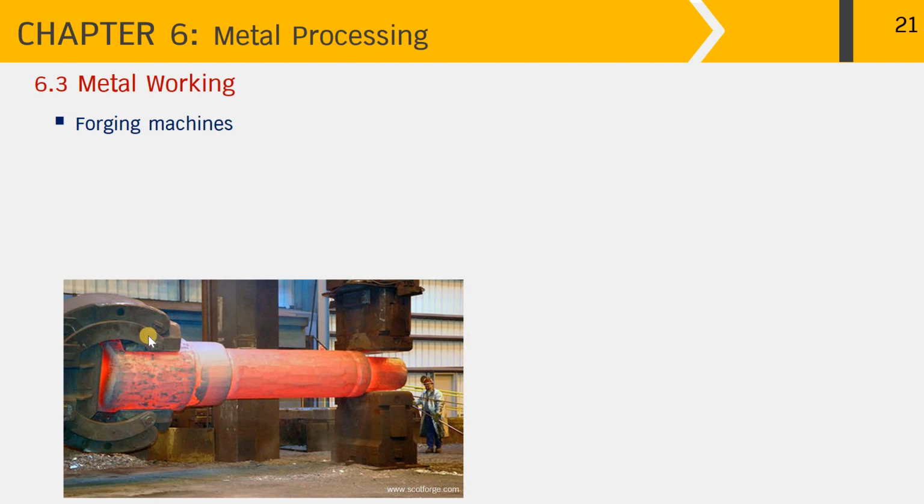This picture demonstrates how hot forging is operated. We need a big machine to do the operation. And you can notice that this metal piece is huge compared to the size of the worker over here, and therefore the operation needs high temperature, that is, hot forging. This big metal piece has been heated up to a temperature of over 60% of its melting point in order to obtain recrystallization, which brings down the yield point of the metal piece and restores ductility, making the forging operation much easier than doing it at room temperature.